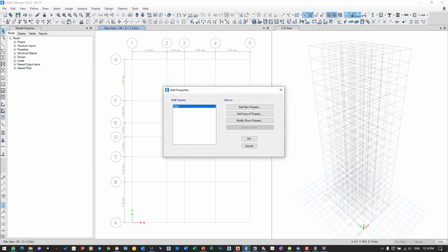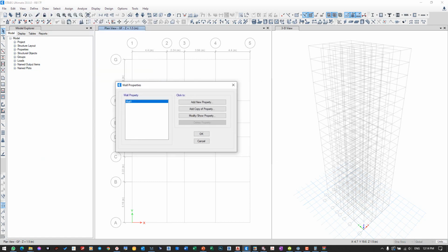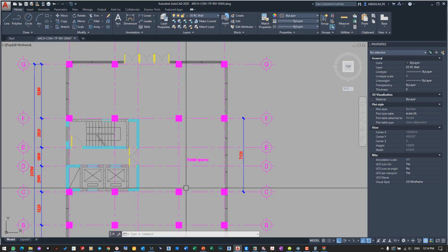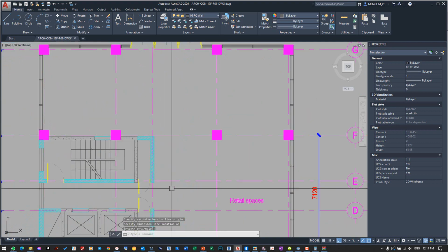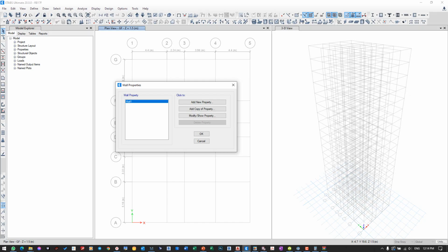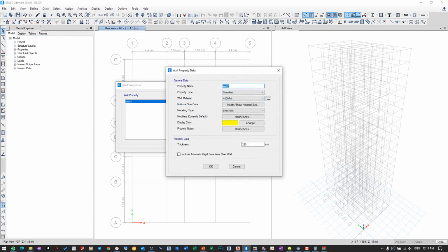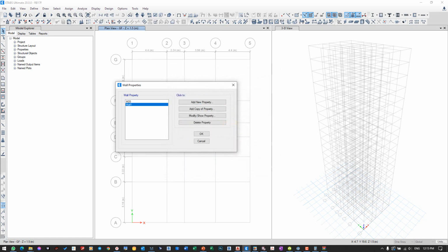And the next we will create the shear wall section. So the wall I will create for thickness about 20. We can estimate it should be 200 millimeter first, or modify, or we can add new property. Wall 20, 30 megapascal, 200 millimeters shell thin, and modifier later we will talk. Okay, and go on, we can delete.